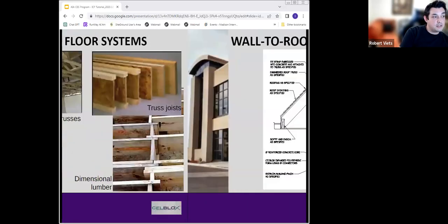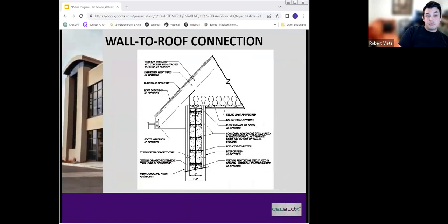For roof connections, if you're doing standard wood roofs, it's pretty easy. You would just do a sill plate like you would on any other normal concrete wall, with bolts, and then your engineered trusses would attach directly to the sill plate, just like normal. In some other areas like Florida and things like that, we do implanted hurricane hangers to set your trusses in. That just depends on your region though.